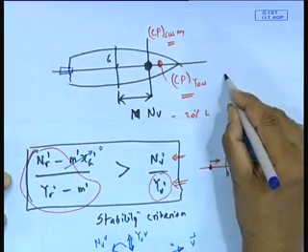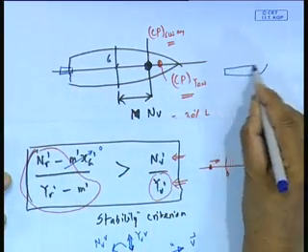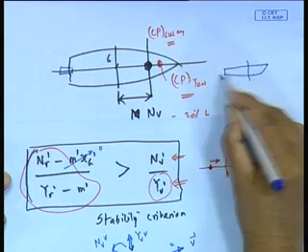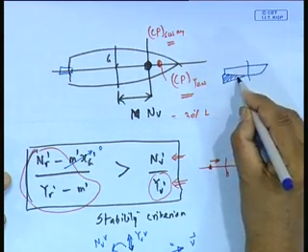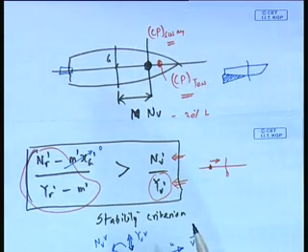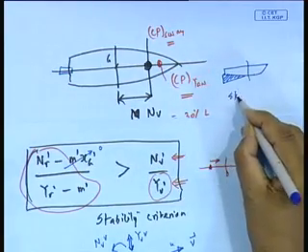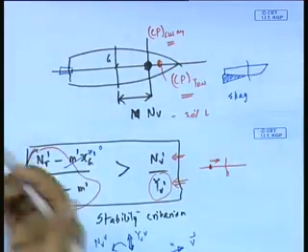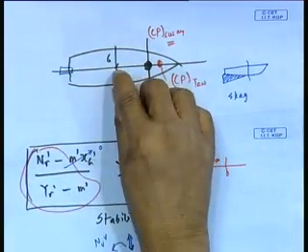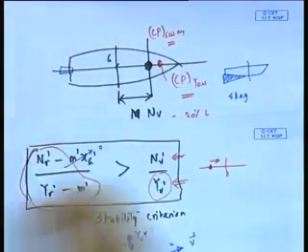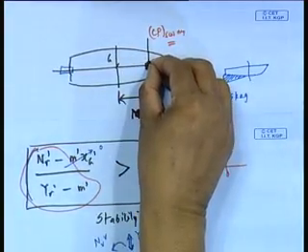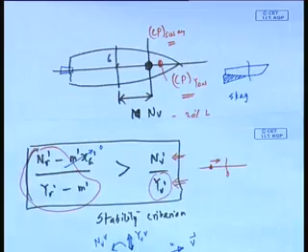There is a hull here, I want to make aft dominating. What do I do? I add a skeg, S-K-E-G, or I add to the forward part, or I can move the CG forward, other way around. So CG forward will do the same thing. Now you understand why for a bow and arrow my CG is forward.